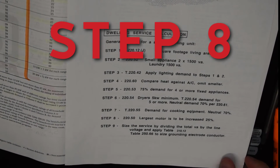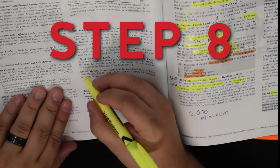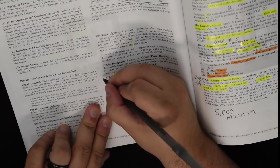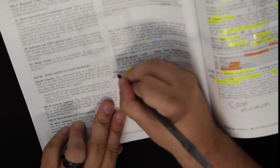Step number 8 takes us to 220.50. It says largest motor to be increased by 25%. Let's go to 220.50. Highlight 220.50. It says motors. Beside it, write step number 8. And this takes us on a journey. That's what it does, and a lot of the code references do that.